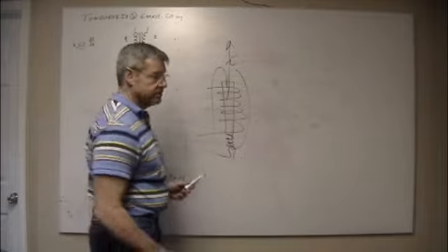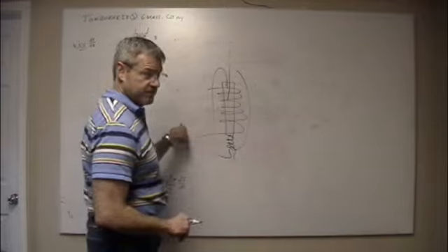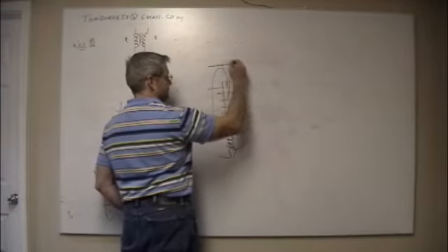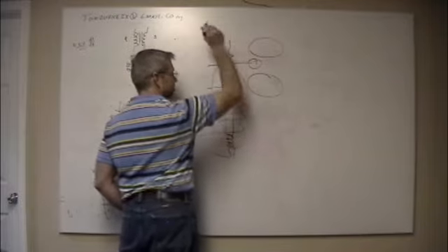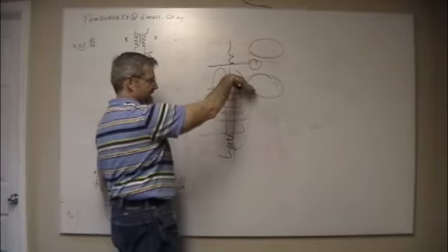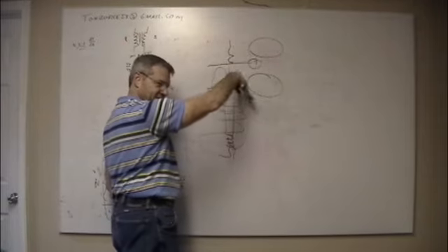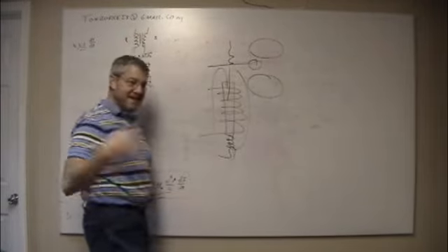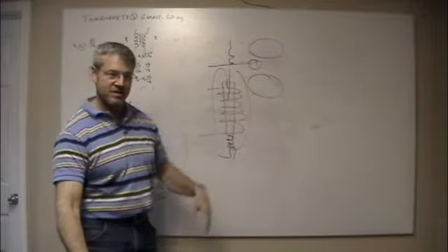Or you can do a relay type thing, an old doorbell. You press the button, and there's the hammer right there, and there's the bells, and there's a spring that pulls it up this way, and it goes clang, and then 60 cycles happens, and it goes clang, and then 60 cycles happens, and it goes clang, clang, clang, ding, with this high-pitched tone that's whatever the resonant frequency of those two bells is.